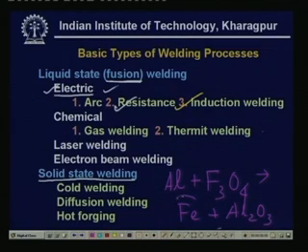Now, here we see this iron is added. But iron is not enough, because we want steel, and as in the iron carbon diagram, in order to make steel we have to add some amount of carbon and other alloying elements, because it is very important to use alloying elements. So normally along with this powder we use other flux materials. This is known as the thermite welding process.